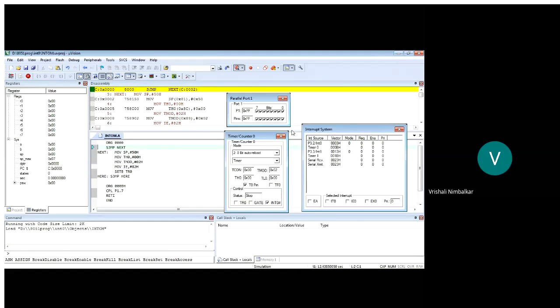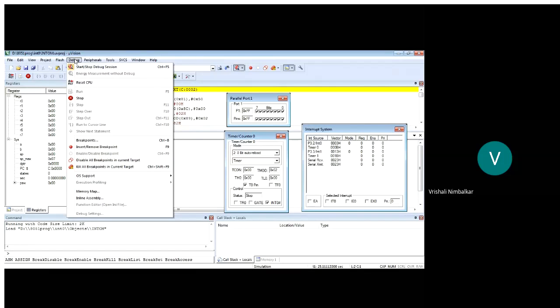That's how we make use of interrupt. The microcontroller is free to do some other operation. It need not keep on checking the flag and checking whether 0.256 millisecond is over or not. We initialize the timer, it keeps on counting up in the background, and when the counting finishes, it interrupts the microcontroller. Then the microcontroller stops the current execution, executes the ISR, which in our case blinks the LED, and returns back to the main program. And in the background, the timer again starts counting up because we have put it in auto reload mode. Is that okay, students?